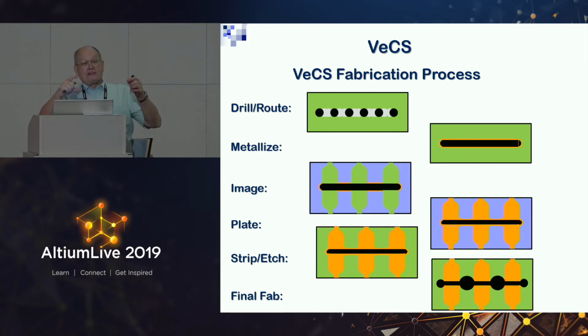Now, this could be done with a big hole. And we come into the hole from both sides, and then we cut it out. So in addition to being a slot, it could just be a hole. But now the via hole, instead of having one net, will handle 2, 3, or 4 separate electrical nets. Big savings in space, but also big improvement in signal integrity.